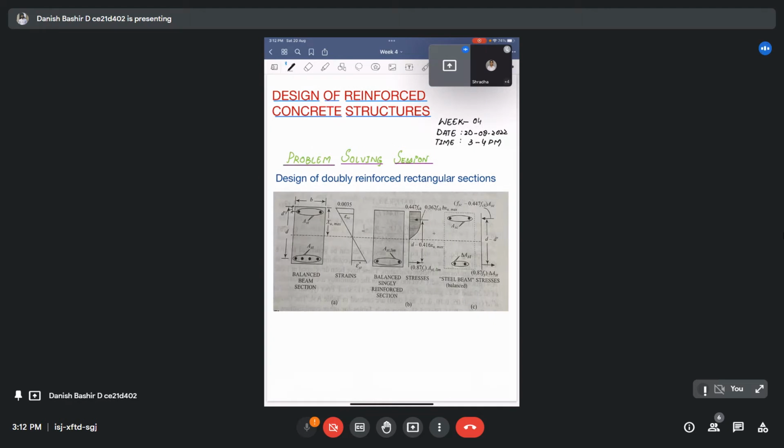Here in this section, you can see this beam section. It's a doubly reinforced section. It is provided with AST at the bottom and compression steel ASC at the top. Now, these are the strains in the fibers. At the top, ESC. We have written this ESC because it is the strain in the compression steel, and we have written this EST, where the T subscript stands for tension steel. Now, I can divide this doubly reinforced section like this.